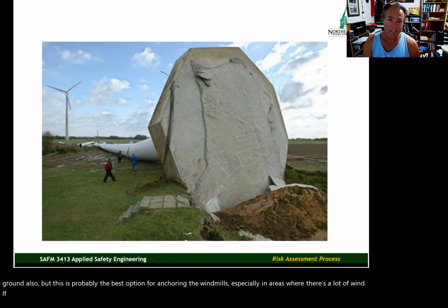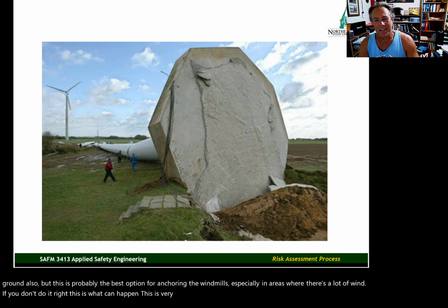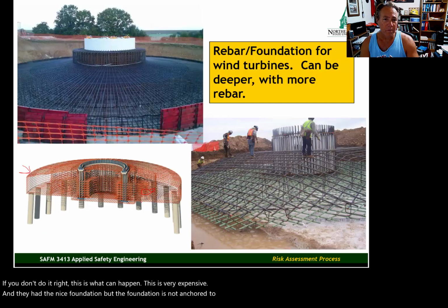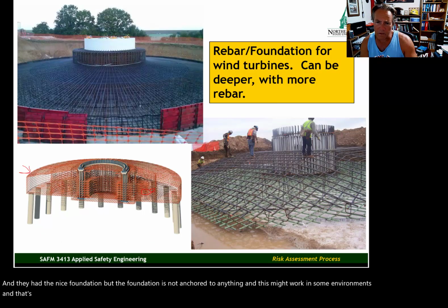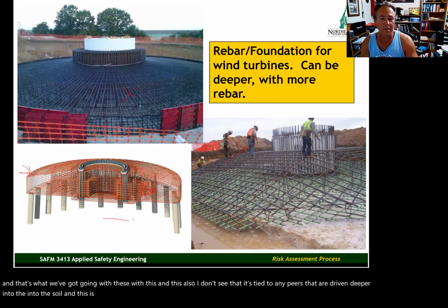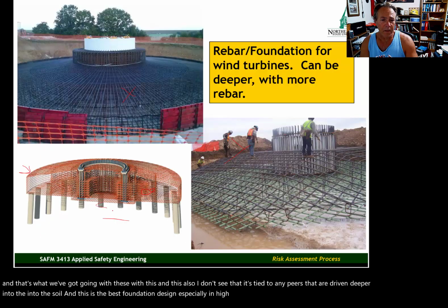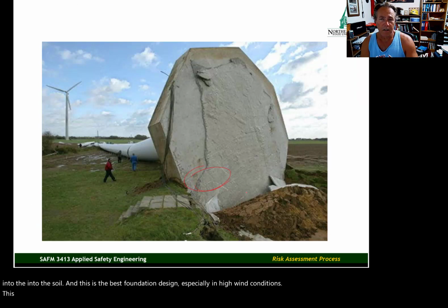If you don't do it right, this is what can happen. This is very expensive. They had the nice foundation, but the foundation is not anchored to anything. And this might work in some environments. Also, I don't see that it's tied to any piers that are driven deeper into the soil. And this is the best foundation design, especially in high wind conditions. This design should prevent this type of incident.